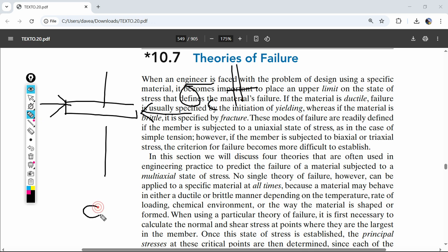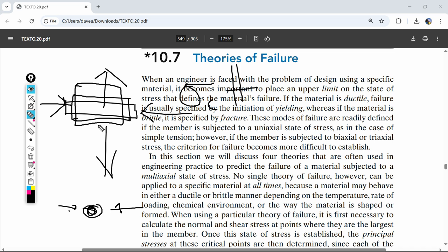And why is that? No, I think the Titanic analogy is good, because when we compress on something in all directions, what happens? It gets smaller in all directions. Poisson's ratio says if I compress in on this, it's going to get shorter, but then it's going to get fatter in all directions. So it's going to look like that. And if I pulled on it this way, well, that's just going to be even worse. It's going to get even larger in that direction.